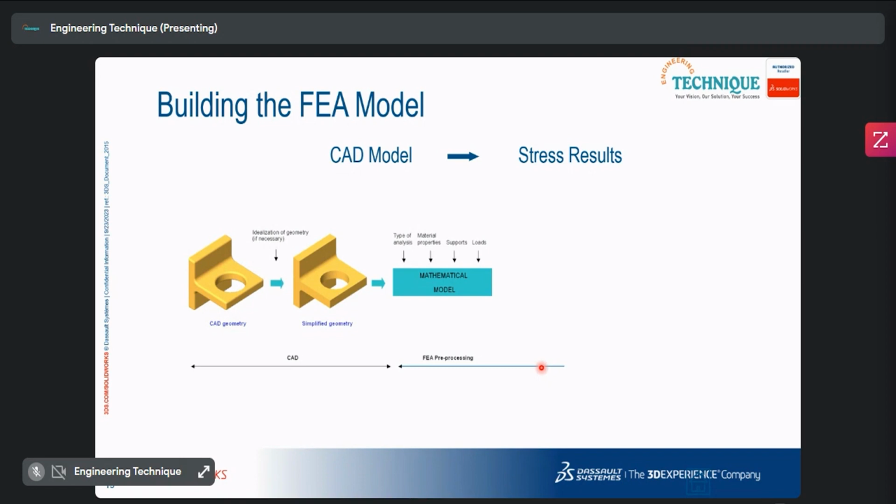That means it is the more aggressive exercise that may depart from the CAD geometry. Suppose the representing thing was within the surface. Okay. Now another thing is to clean up the CAD models. The overlapping edges and surfaces need to be cleaned up before the simulation, otherwise it will create difficulty in the simulation. Now, this is the CAD pre-processing part.